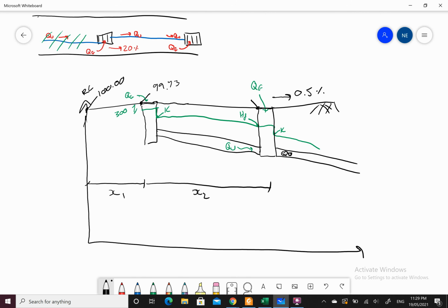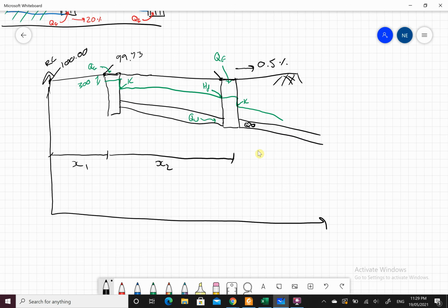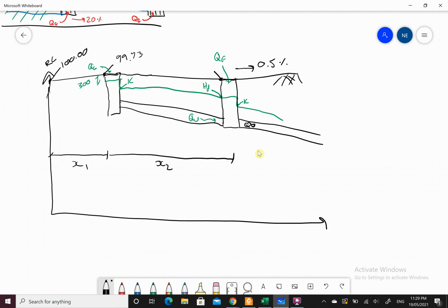The other thing that you'll need to have a look at is our minimum pit sizes. All right, that there is also going to be important. If you're going to assume your pipe's going to be full, we might need to drop our pits further down to ensure that our hydraulic grade line sits below it. So that's our overview for our assignment.